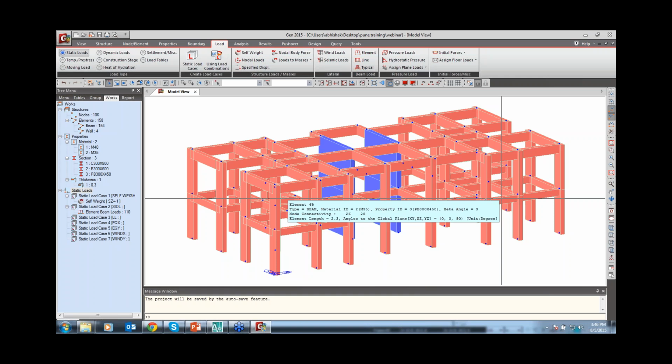Yes sir, two more nodes are required to generate the model. Otherwise, we can say two more beams are required: the first beam breaks at one junction and the second beam at the end of that shear wall. So these two beams you have to generate separately, and then you can apply the wall load.